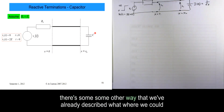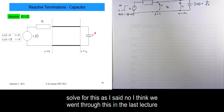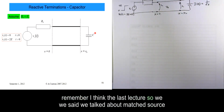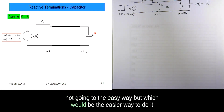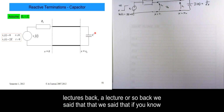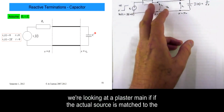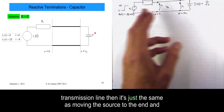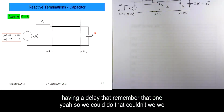But is there some other way that we've already described where we could solve for this? This is Z naught. I think in the last lecture we talked about matched sources and loads. Which would be the easier way to do it, considering that RS equals Z naught? Remember a few lectures back, we said that in the Laplace domain, if the actual source is matched to the transmission line, then it's the same as moving the source to the end and having a delay.